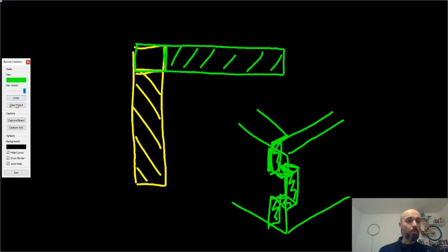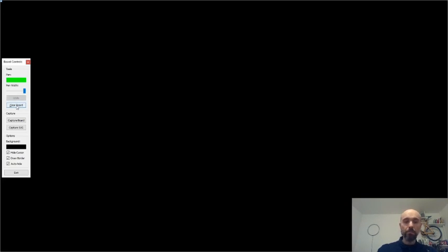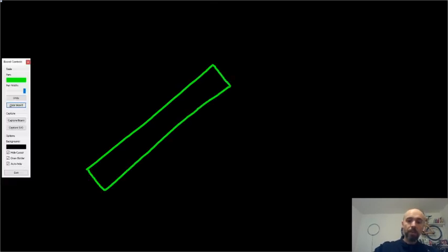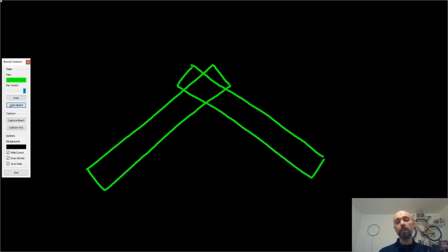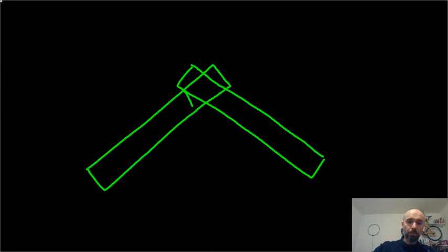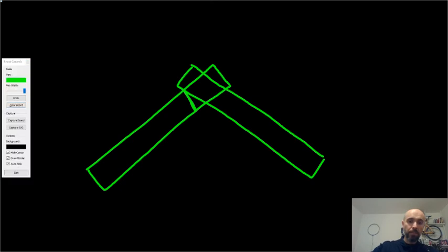Now, when you change the angle, things change quite drastically. So if I have something that goes like this, for instance, and the second one is not at 90 degrees, but it's, let's say, a bit more. Now, the laser cut can only cut perpendicular cuts, at least the cheap one. So let's consider that a rule. That means that the cut in this case is going to be like this, and the cut in this case is going to be like this.